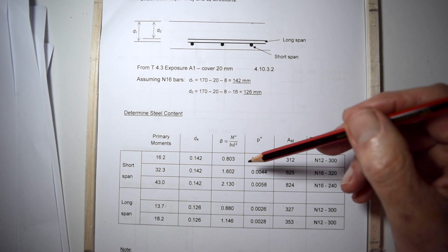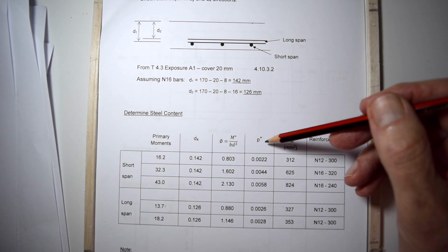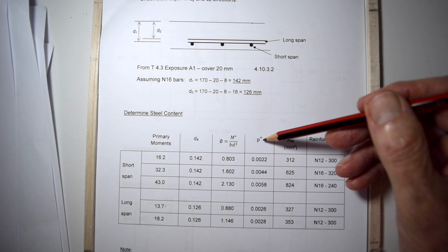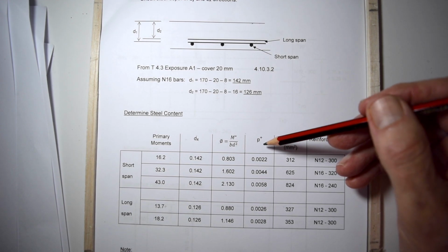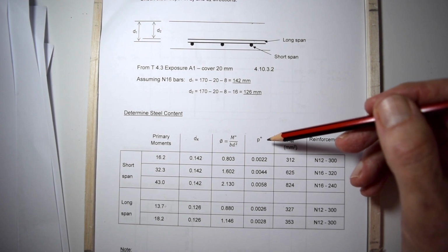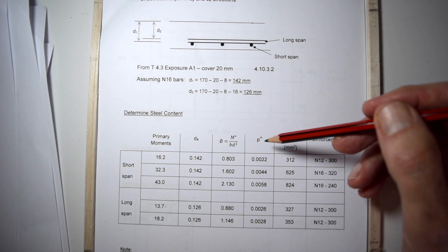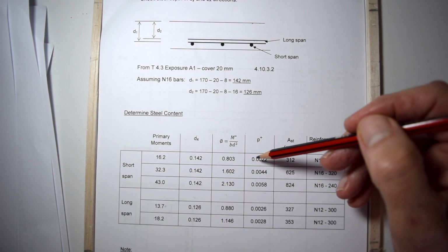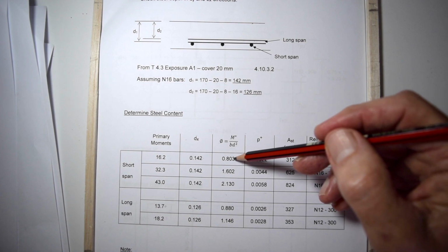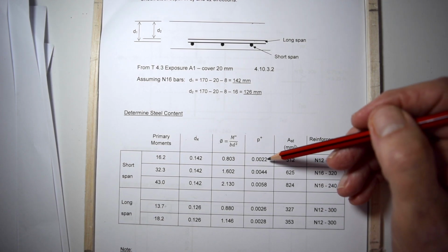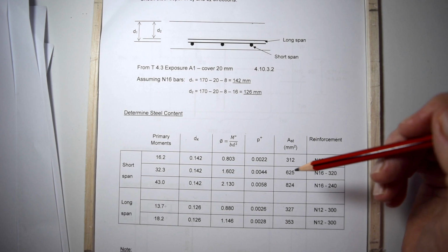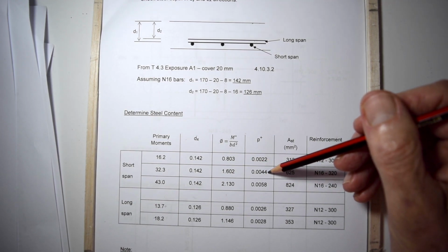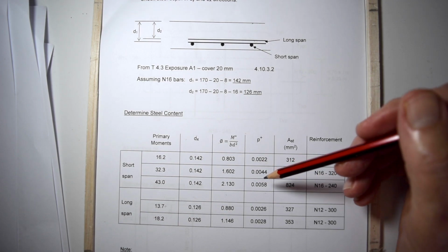Our steel ratios that we get from that, because the steel ratio, as you remember, is the area of steel is p b d, so we have to work out what p is. We look at the graph and we find out what p is. In this case, for that M over b d squared, or that lambda, it's 0.0022. For this moment there, the p is 0.0044 of your graph.